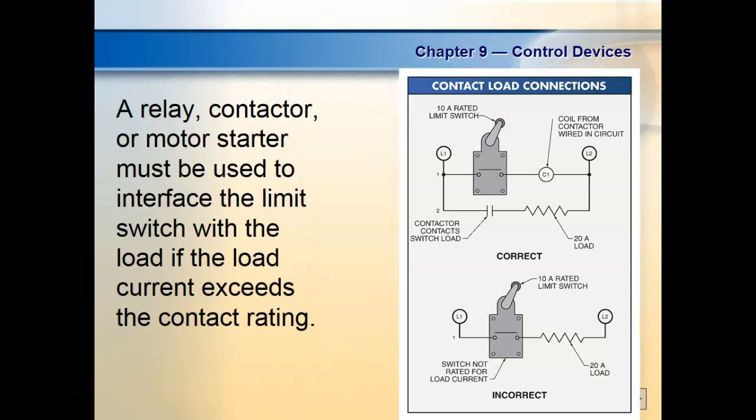So you go out and look at a fuse. A fuse for a car is rated at 12 volts. You take the same fuse and put it in your house, and you're trying to break 120 volts, and it could do what? It could arc across and cause problems. So anything that tries to break a circuit is going to be rated in how much voltage it can break and how much current we can put through it.